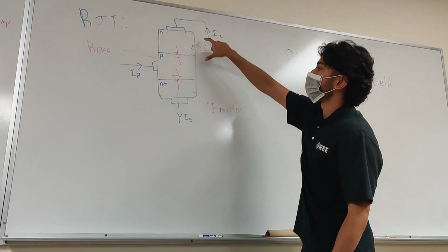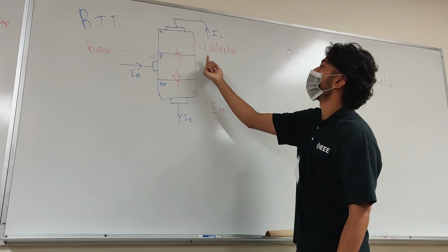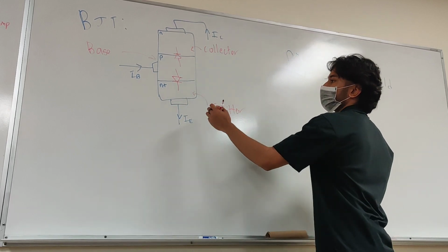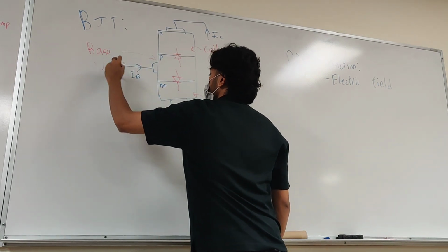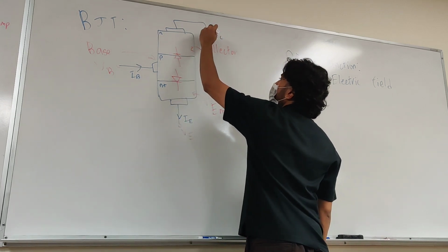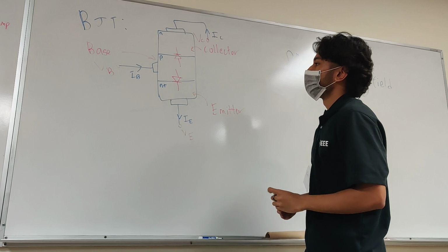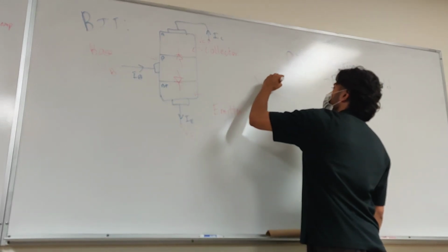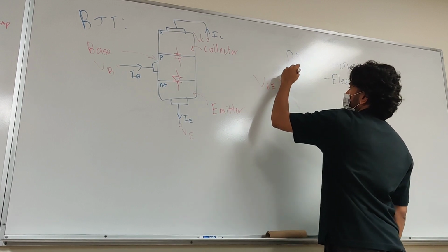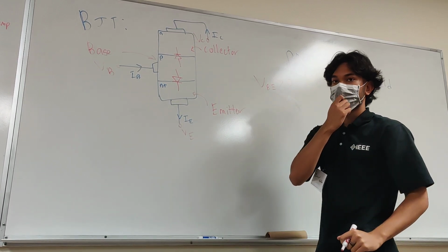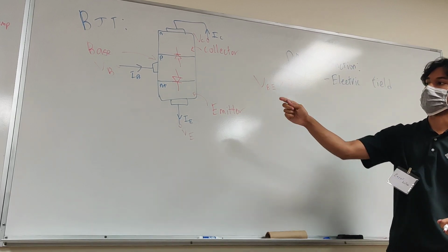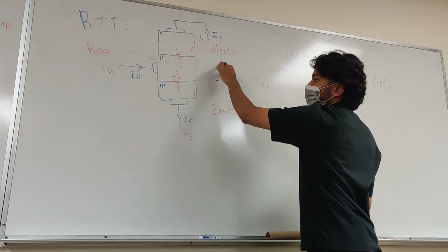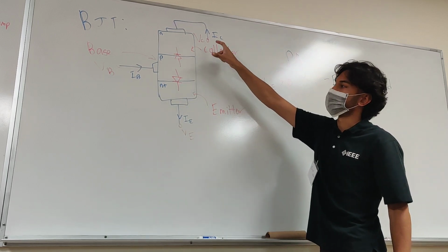Great. We want this one to be reverse biased. So this means we want to continue having electrons going up this way. But we don't want any to go down this way. We don't want any to go in the opposite direction to cancel out all the work we did over here. So what happens is we have our base voltage, VB. We have a certain emitter voltage, VE, and a certain collector voltage, VC. Okay? So now we want to bias this so that this junction is forward biased. So this means VBE we want to be greater than, well, let's just say 0 for now. It's not actually 0, it's around 0.6, because your diode has a certain voltage it needs to turn on, that V phi over there. Let's say 0 for now. Similarly, we want VCB, right? We want this to be greater than 0 so that our collector is higher than our base. So this is off, right?